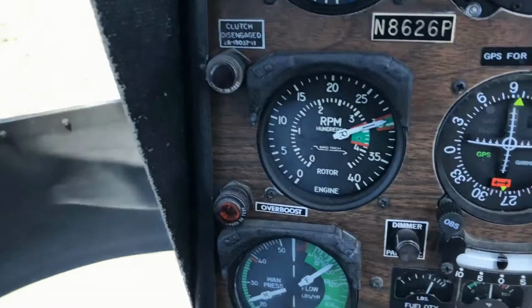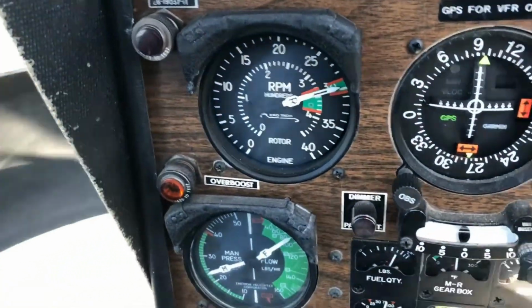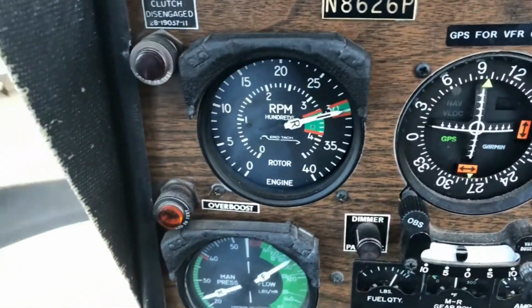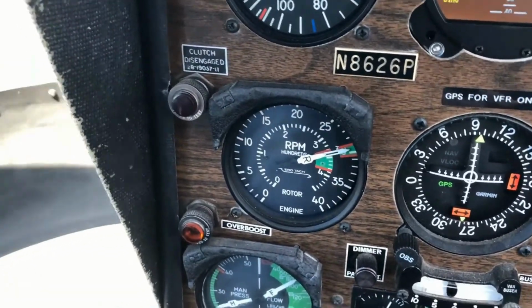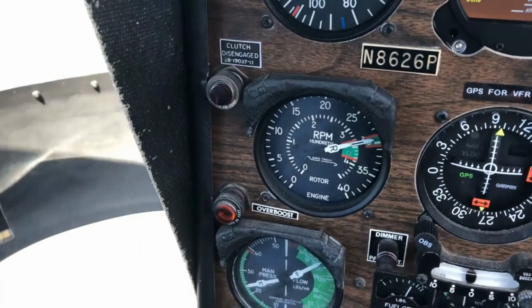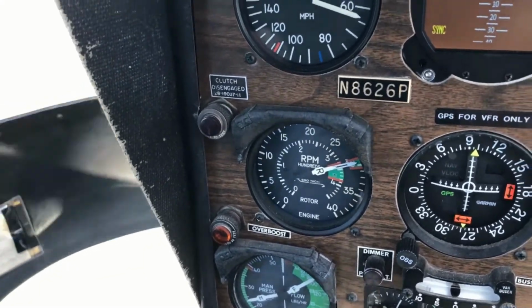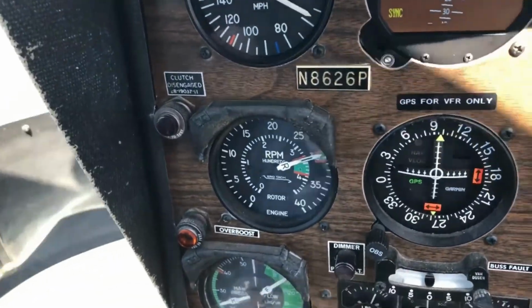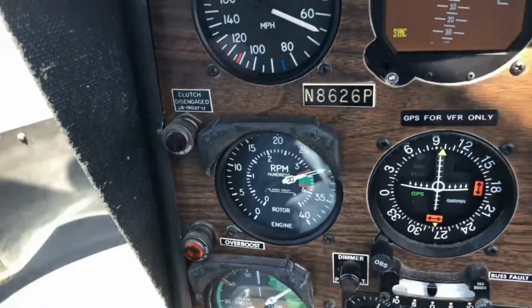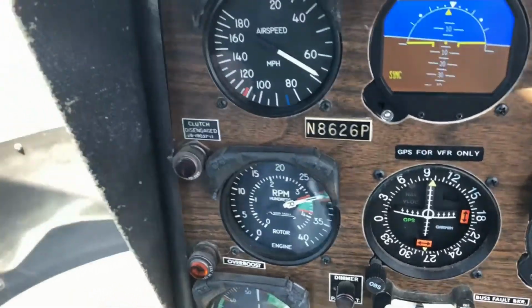Okay, so very important here, anytime you do an autorotation, you put a turn in there, that rotor RPM is going to increase. It's going to always happen. So we're going to try to catch that with the camera. We're going to try to know where the RPM is when he first enters, and then we're going to watch it rise a little bit during that turn, and then Gary's going to raise the collective to keep it from going past the limitation.